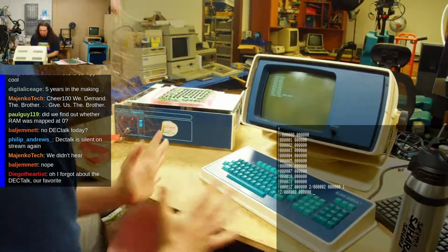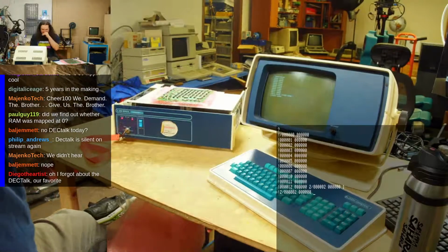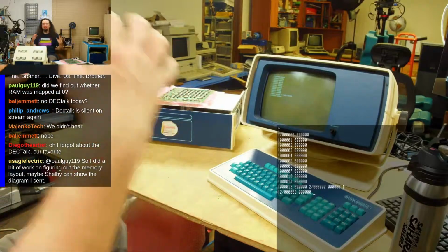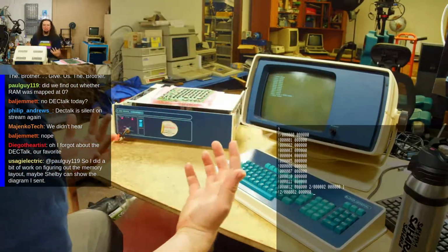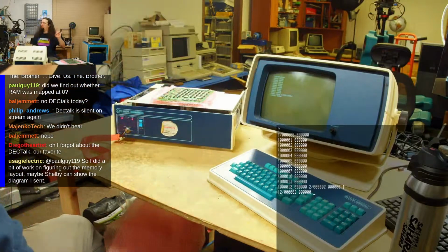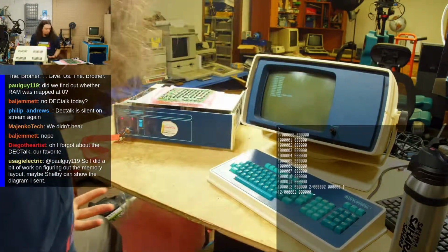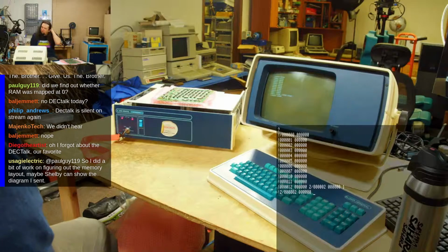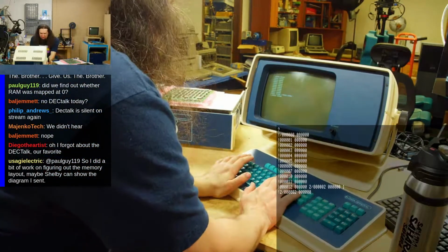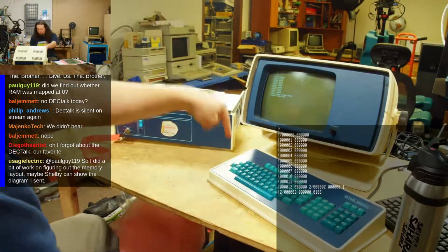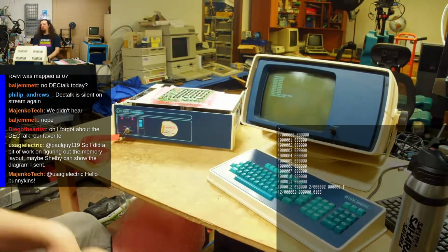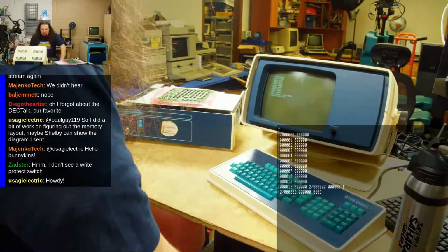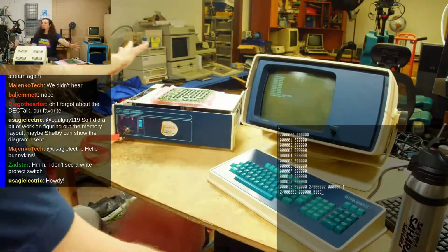Okay, so let's go over some stuff. We should be able to read and write at this point in memory. What you're seeing there, address 2, is the bootstrap data location for the microNOVA. If you were going to load off of a paper tape, you needed to program in which device to look for there, although not exactly, because you can also put in, I believe, a 4-digit code and then press Shift L to enter device loader mode. That should use the serial card with the extra bits, which would look for a device address and try to read the code on it.